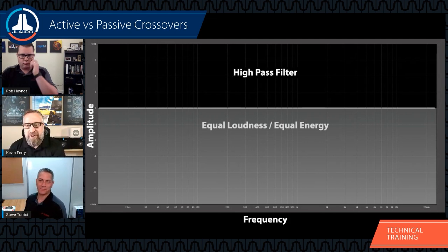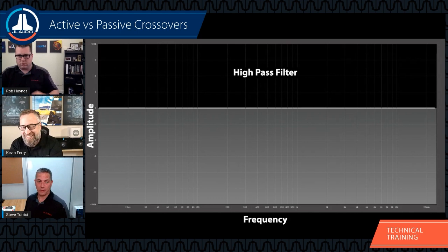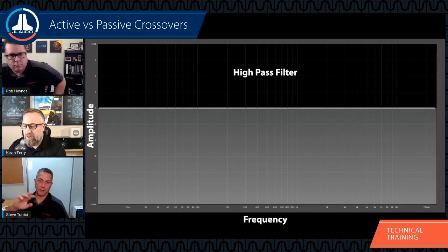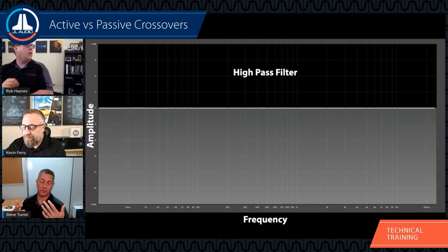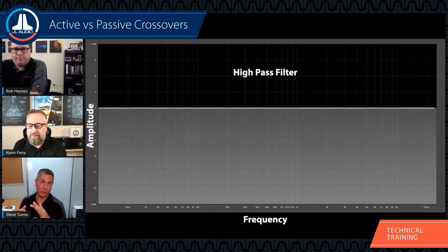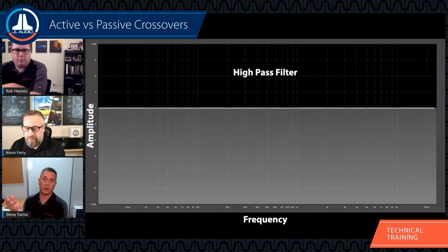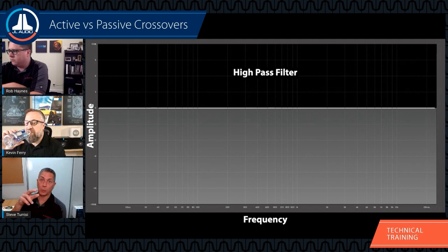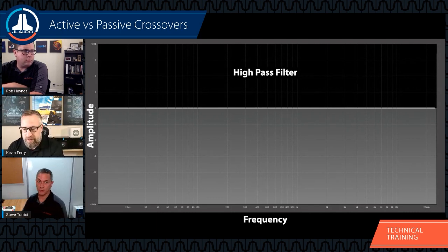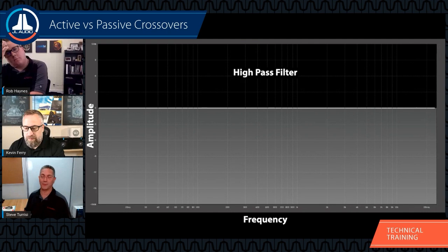So what we want to do is use a lot of the curves you showed earlier about high pass and low pass filters. What effectively happens with a subwoofer, or any driver that has a limitation as it gets lower in frequency, is it becomes almost like a mechanical filter, in that it can no longer produce output. That's why when you look at enclosure design software, you'll look at the low end response and invariably it will taper off like a high pass filter. That's because the mechanics of the speaker prevent it from playing those lower frequencies. So it's kind of an interesting, although weird, way of looking at it. We have electrical filters, and here's a mechanical filter in practice.